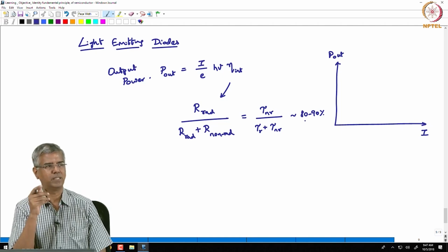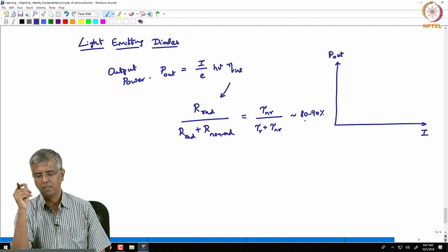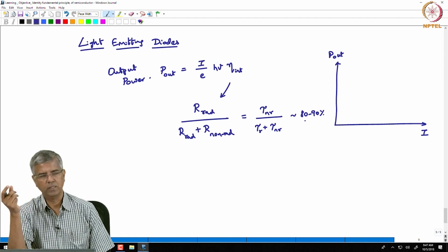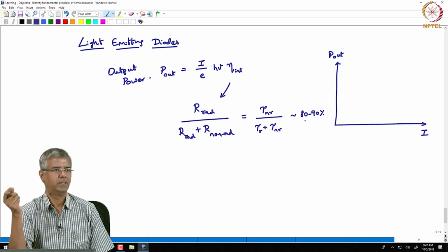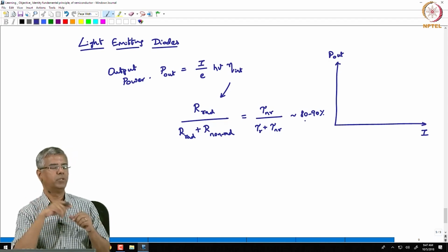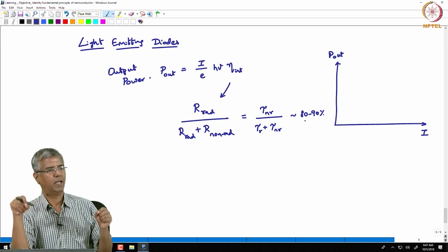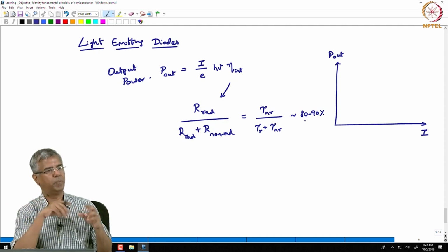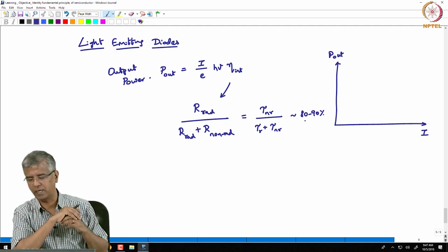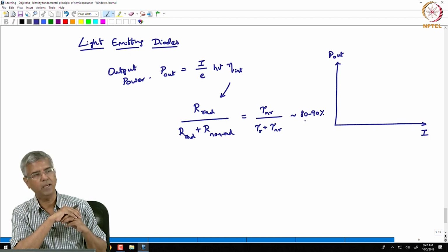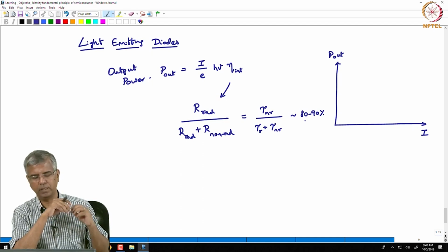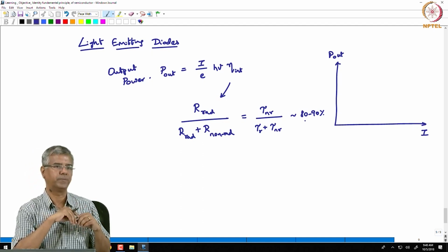In silicon, the story is different. We understand that it is an indirect band gap semiconductor. So, there is no direct recombination that is happening. That recombination would have to be associated with typically a phonon or a vibrational mode that takes out that extra change in k, the momentum, and that means your eta int is much lower.